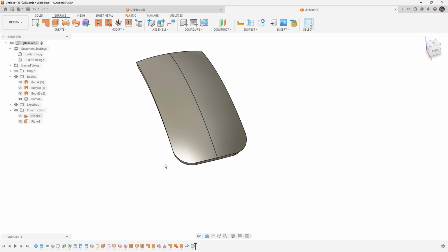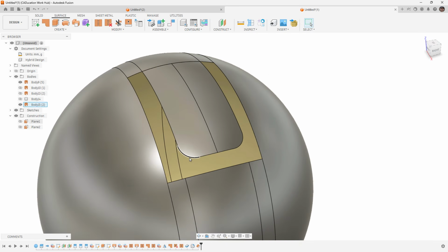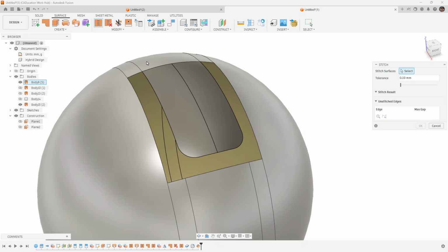So at this stage where we're at, it makes the most sense to fillet those as a solid and then use a tool like offset, which is going to create a copy. And then we're left with, let's go back to this one here, this surface that's got those nice rounded corners. So I'm going to stitch all this back together.